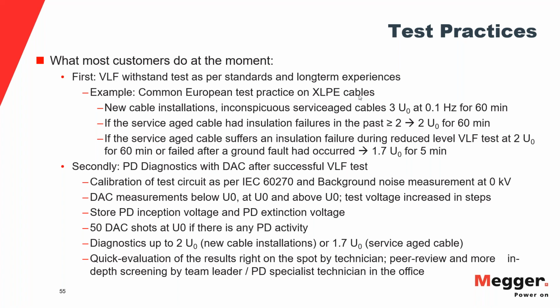You have to do the voltage test, which is the withstand, as per whatever governing body you adhere to, IEEE or IEC. Let's go with the IEC numbers here. For instance, in Europe they would do 3 times operating voltage, 60 minutes at 0.1 hertz.